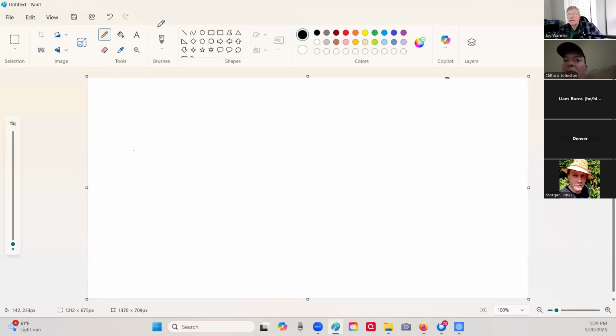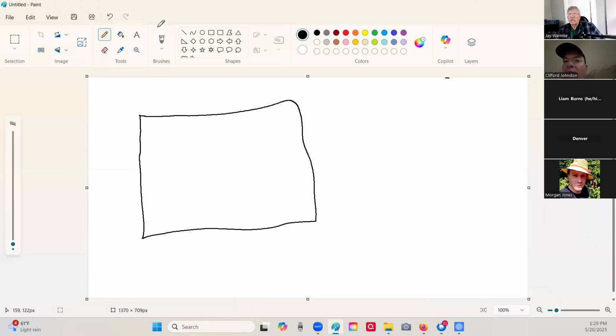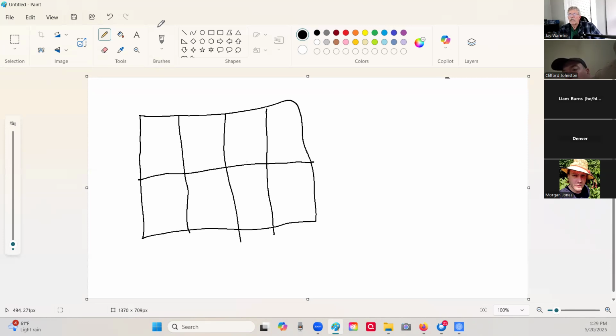let's say I've got a solar array here. And for simplicity's sake, say that I've got 8 solar panels, right? And they're all hooked together in a string. So all of these are going positive to negative, and so on and so forth. And then we come out of here, we go to a junction box. But all of these are connected together in one string.